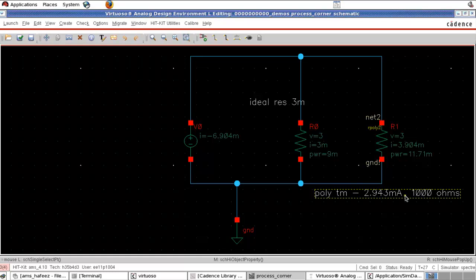You got the point. What we targeted is 1000 ohms, but due to the variation in the process, instead of 1000 ohms, we got only 770 ohms. So this is the maximum variation, the maximum decrement you can expect from this AMS process. This is modeled by the manufacturer, so we can record that.